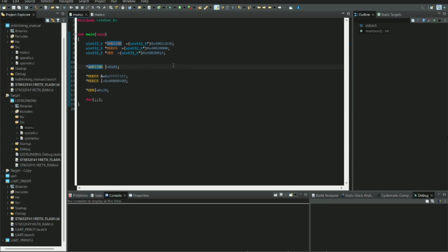And this is a register in the RCC that is used to enable or disable the clock signals to peripherals connected on this bus, which are the GPIO ports. As my classmate said, if the clock for a peripheral is not enabled in this bus, the peripheral won't function. So we're going to use the OR function to set this value.